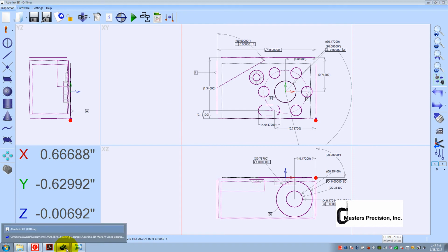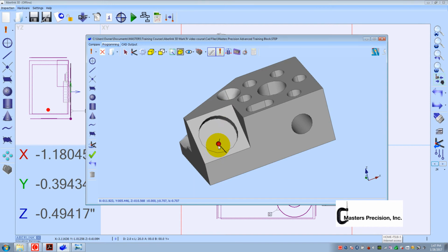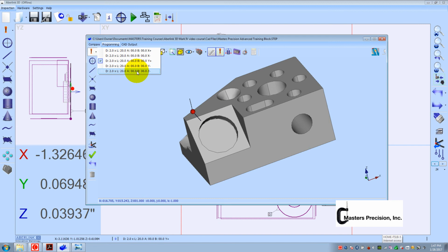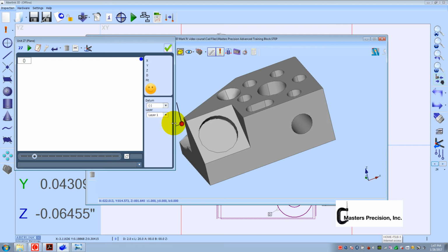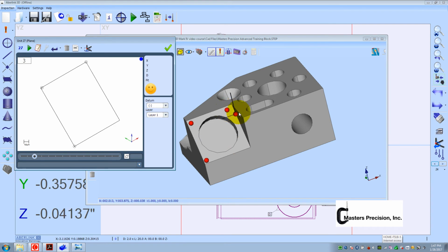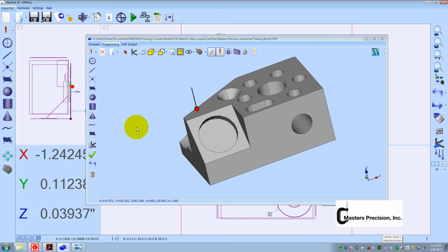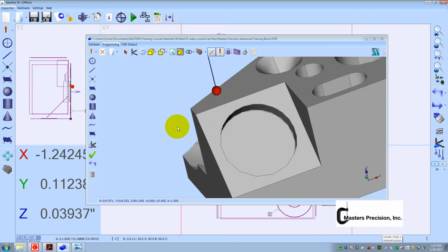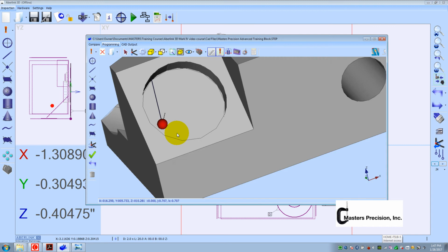So let's go back to our CAD. I need to change my probe again. I want to go straight down with this one. And because I am using a fixed head, I cannot rotate it. I'm limited as to what I can do, so I'm going to measure a plane right here. Actually, I'm going to come back up top. I don't want my star to hit this wall. So I'll say OK to that.